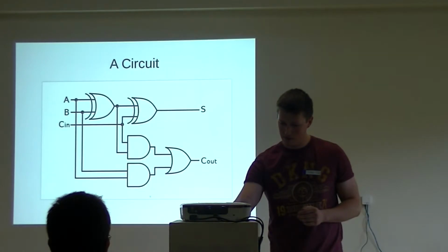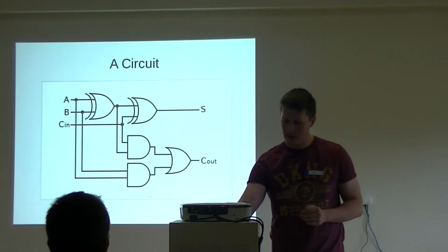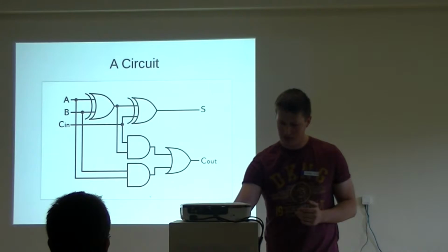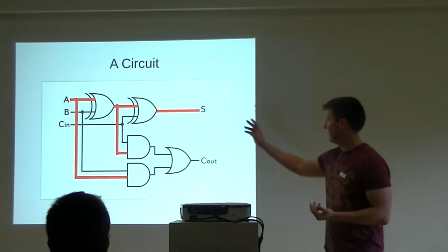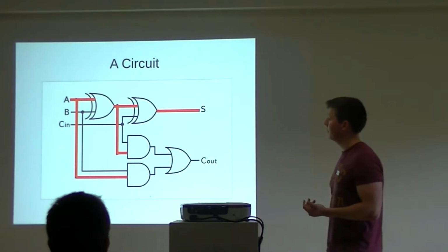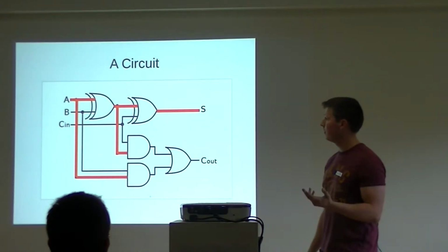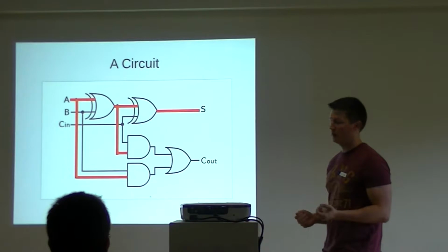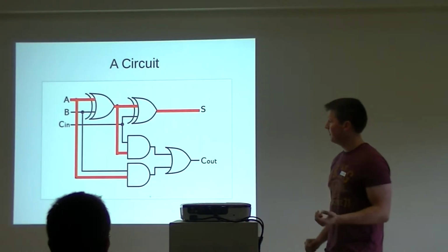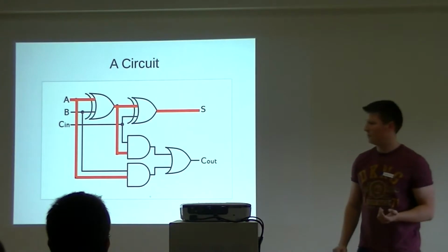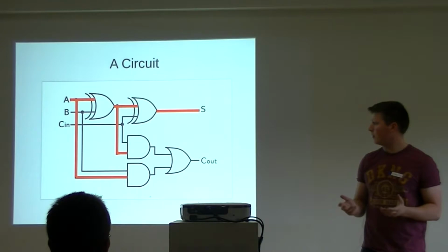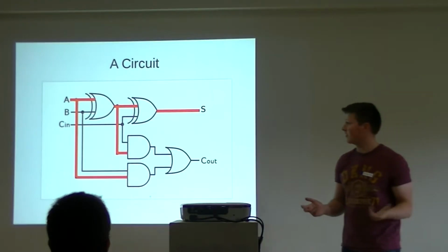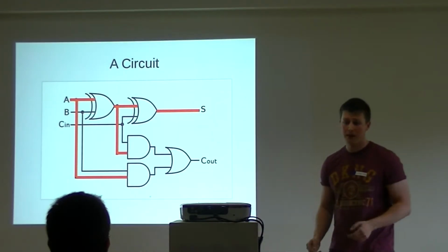You can see this more when we have a more complete circuit. So if I was to flip the A line, this also toggles this intermediate line and the S output. So by toggling this one line, I get 3 lots of energy consumption. It's not quite that simple, but it's a rough guide: the more complex the circuit, the more internal flips you're going to get, and the total amount of energy is going to be larger when you flip one line.